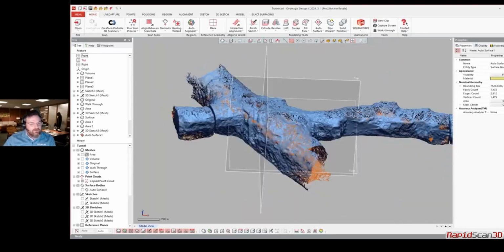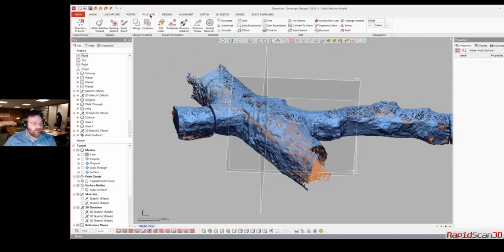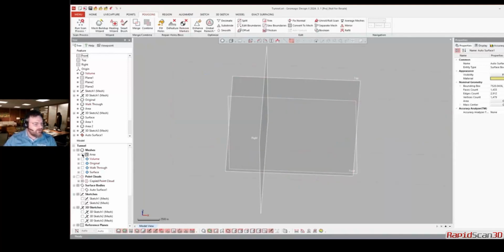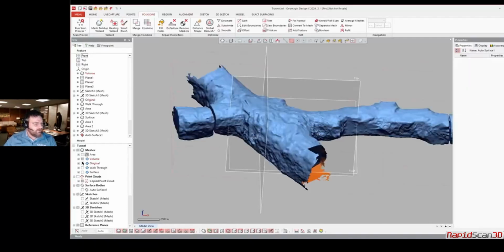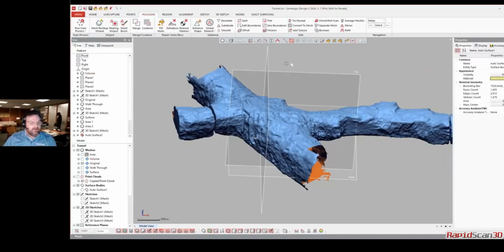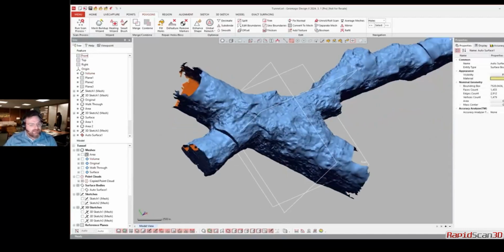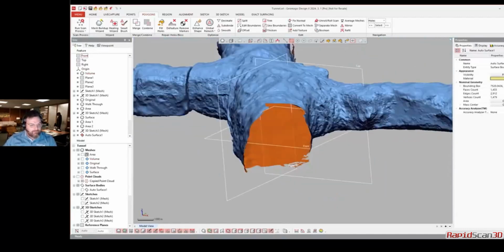And what you can do with this is it's a point cloud over here, but you have the ability in here to come over and merge and triangulate this object into a mesh. So I'll go ahead and turn that off and we'll just show what the result is. So you can triangulate that into a polygon mesh.